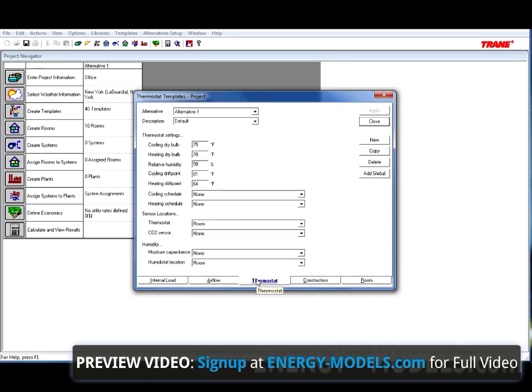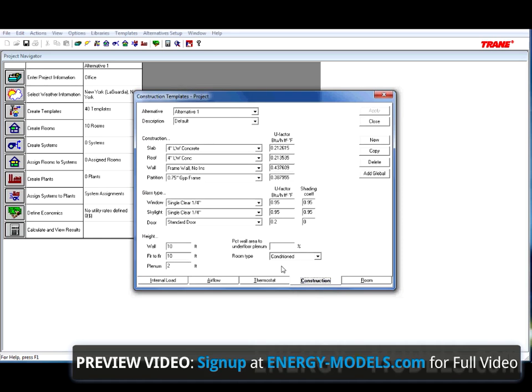Another field that is enabled is the room type, defined under the Construction template, as well as the Rooms tab of Create Rooms. There are only two options, conditioned and unconditioned. You will only need to enter this field when you wish to add an unconditioned room, that is, a room whose lighting and miscellaneous load energy is taken into account, but a room that does not affect air conditioning and heating energy.